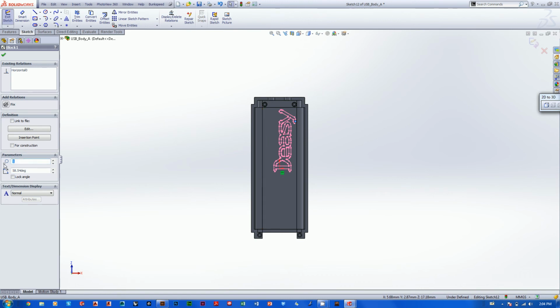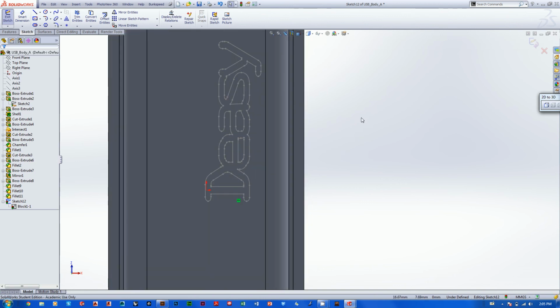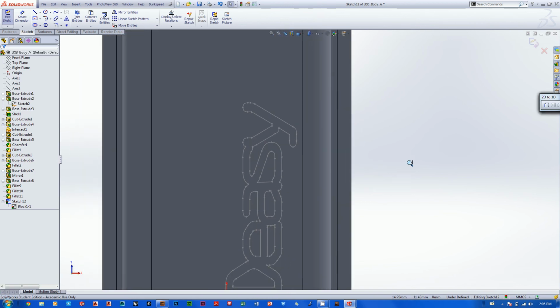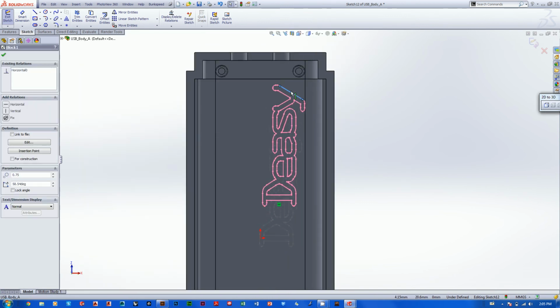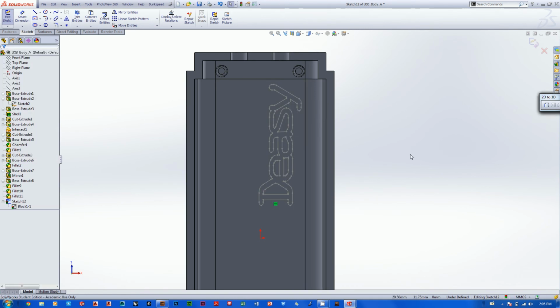So over here with this parameter box with a small and a big circle, that's your scale box. So you can just go 0.5 and you can scale it down a little bit. Actually 0.5 is a bit small. Why don't I say 0.75? That's better. Okay, and when I click off the block, it turns gray, but I can always grab it again and just move it anywhere I want. Fantastic, just like that.